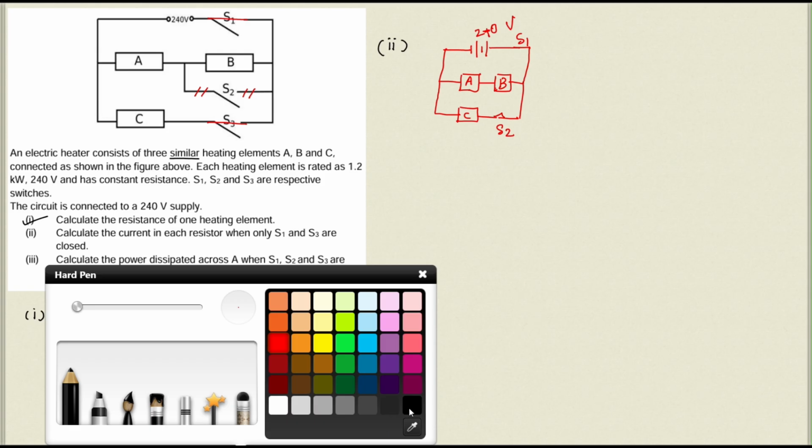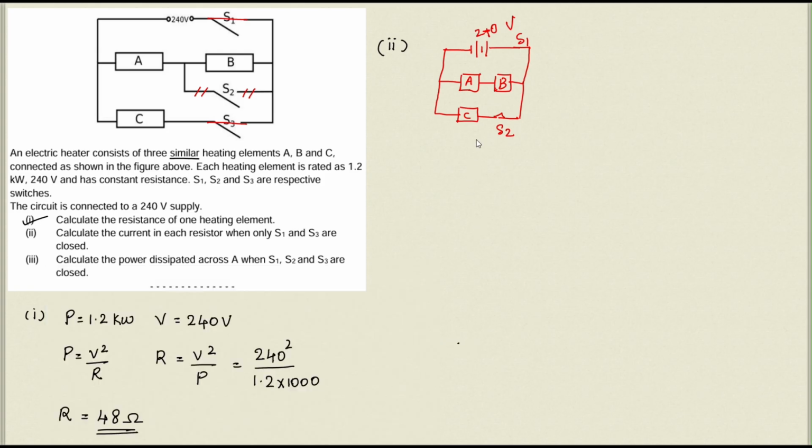So in this figure, we have to find out the current in each resistor. So how much current passes through A, B and C. Just imagine that the total current in the circuit is I, as AB is parallel to the input voltage, C is also parallel to both AB and input voltage. The current will split up once it reaches this junction. So we can imagine let I1 current passes through this point and let I2 current passes through this point at this junction. So we can say I2 current passes through C and I1 current passes through A as well as B because they are in series.